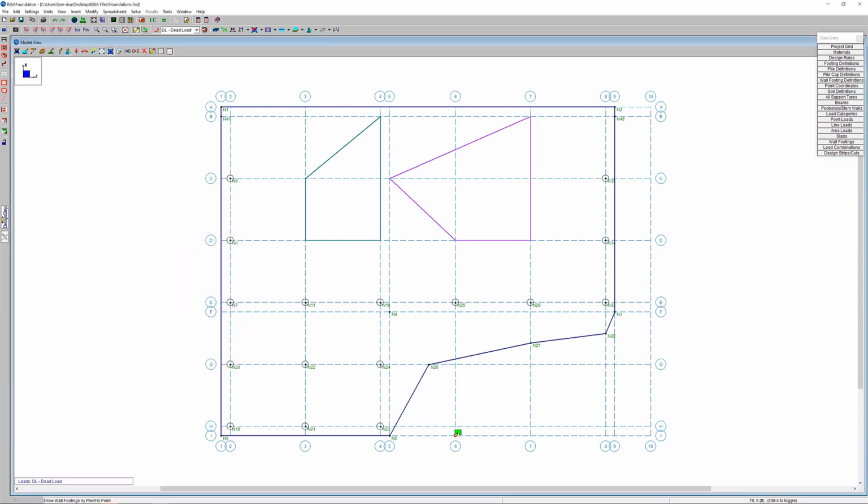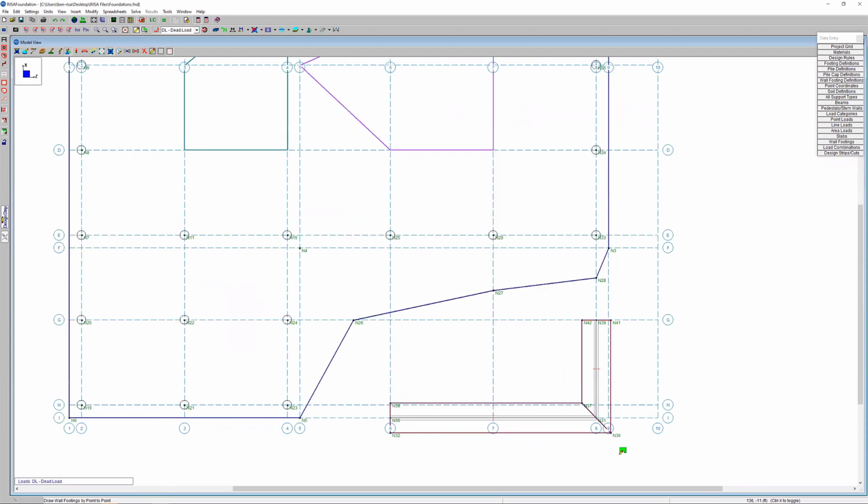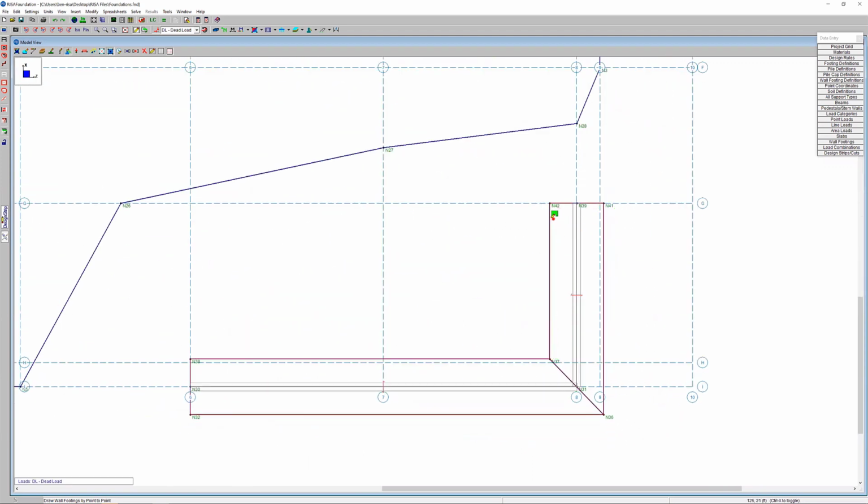So that's fine. And then if I start to draw, so here to here to here, you can see that because I'm modeling a slab, it's modeling a slab underneath here with a design strip, and it's going to give me that corner appropriately, because we don't want that overlap. Previously, I'd have a slab that would end here, a straight line end here, and then another slab that would straight line end here. And that wouldn't be overly useful, because I would get this overlap and this interaction between those slabs that didn't really exist. And so this gives me a more accurate look at what's happening here.